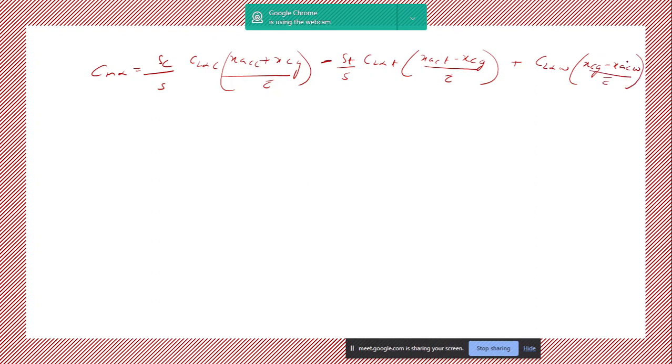Okay, so for neutral point, how did they ask us to find out the neutral point? How do you find out the neutral point from this equation? What is neutral point? Exactly. So you set Cm alpha equal to 0, and the CG location where Cm alpha equals 0 is the neutral point, right? So what will it be? Yes, so Cm alpha equal to 0. So if I set this as 0 and replace this with NP.